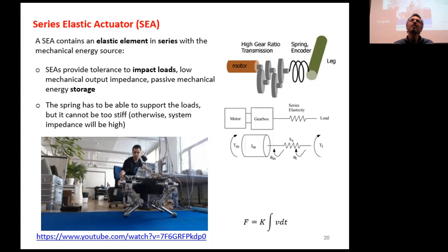Why? You don't have to take into account the elasticity of the position. There is always some elasticity in the wall, even if it's perfectly rigid. The thing is that this elasticity, or stiffness, is very high. So for every motion of the actuator, the force is the integral of the velocity, because the elastic force is K times the deformation, but you could see the deformation as the integral of the velocity.